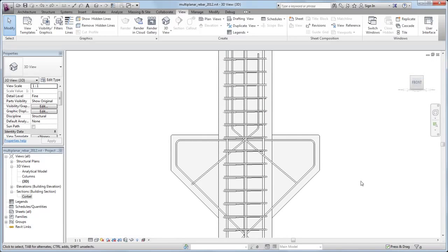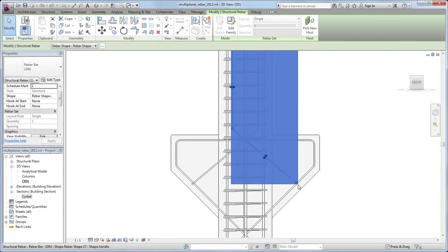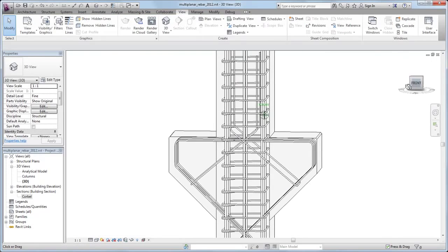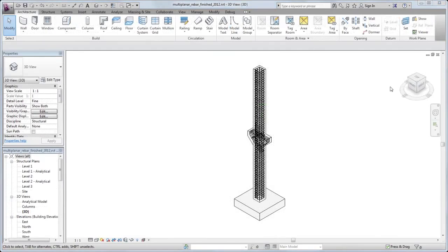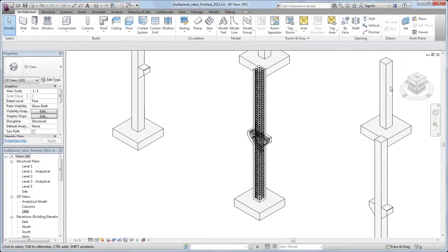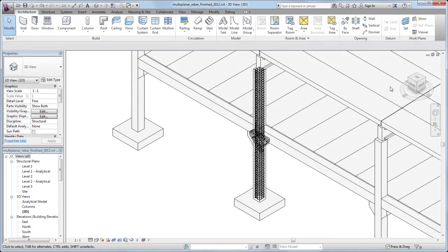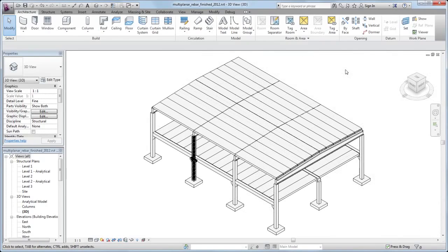After repositioning the rebar, inspect the placement in a 3D view. Again, look for instances of geometry intersection near the stirrups of the corbels and make further adjustments as necessary. Using these sketching tools for multiplanar rebar will facilitate the complex detailing of common reinforcement in your structural model.